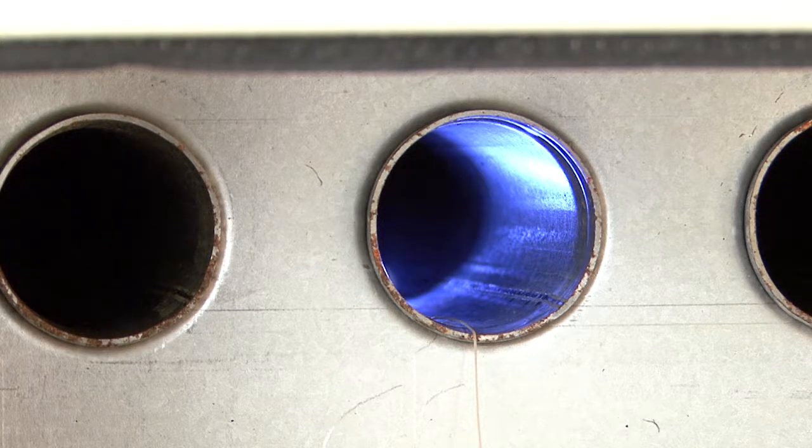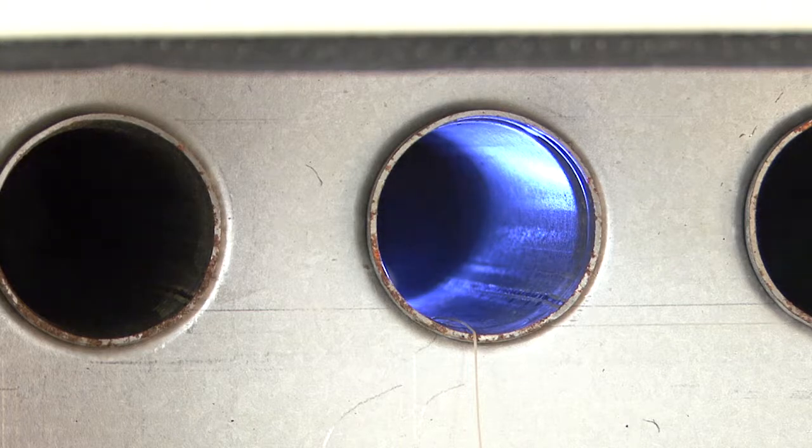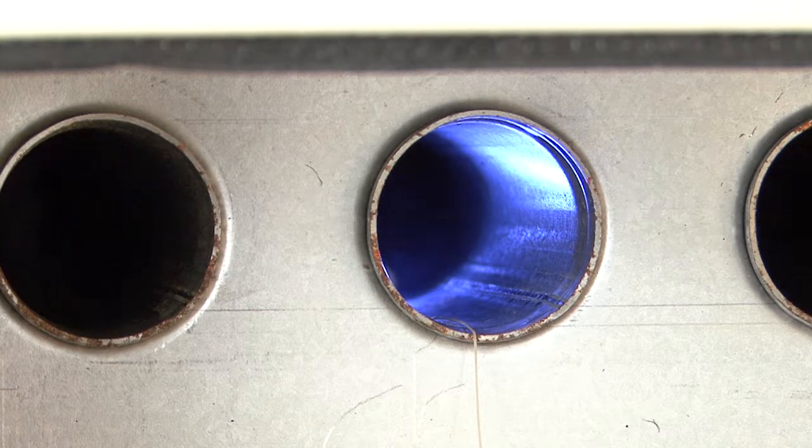The primary reason is the fact that the incense stick, all it's going to do, if anything, that you're going to drop in that heat exchanger a little bit, is a little bit of ash. And a little ash in there, it'll make its way down into the secondary heat exchanger, but it's not going to hurt anything. If you're using a candle, you're possibly dripping wax up inside that heat exchanger. You don't want to drip wax inside that heat exchanger. Gotcha. And also, the incense stick does a real good job of creating enough smoke that it's going to answer your questions for you.